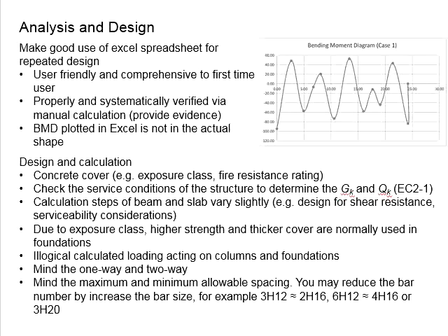It will depend on the degree of spacing between the columns, as well as the estimated areas covered by the respective columns and foundations, so that in relative comparison you know the magnitude of the load acting onto those members. From there, at least you have an idea whether your calculated result is logical or not.